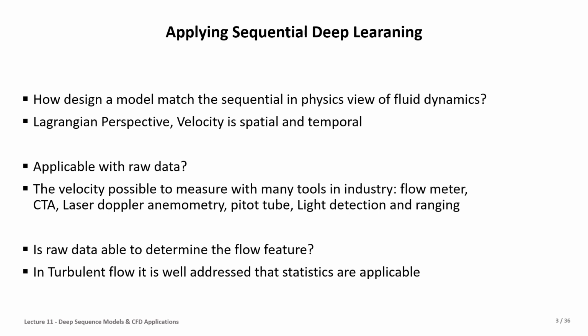These data could be applicable as a time series, like the flow meter, constant temperature anemometer, laser Doppler anemometry, pitot tube, and light detection and ranging.